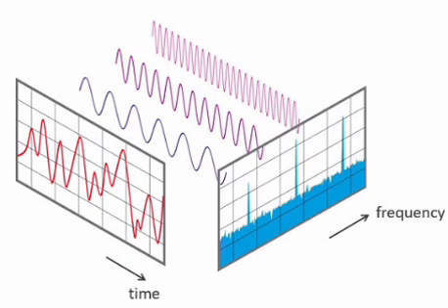The fast Fourier transform is a discrete Fourier transform algorithm which reduces the number of computations needed to find the transform. For an N point DFT, the number of multiplications equals N by 2 log N base 2, and the number of additions equals N log N base 2. Remember, multiplications: N by 2 log N base 2; additions: N log N base 2.